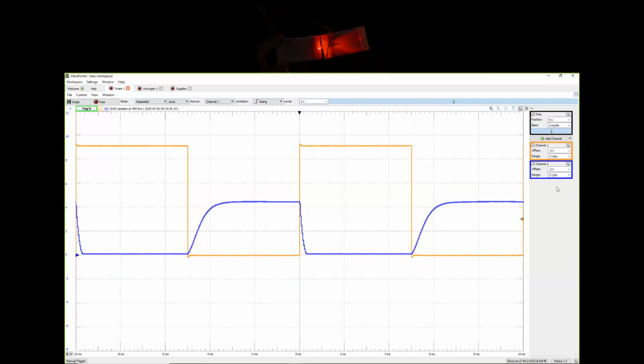As you can see, when there is light indicated by a high voltage on the wavegen, we measure very small voltages on the output like we established in theory. And when we have a low voltage at the wavegen, we measure something that is high. It is close to about 5 volts here, as you can see.